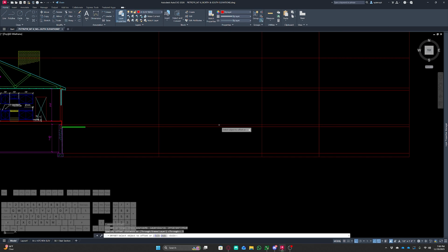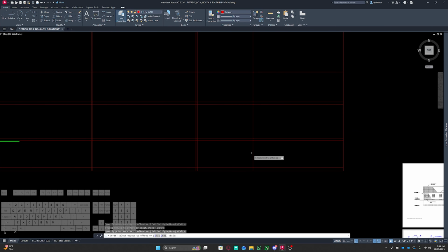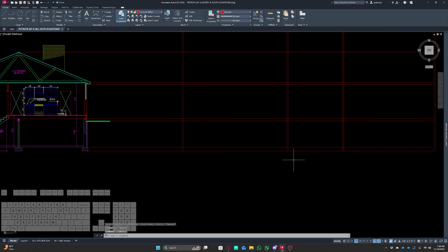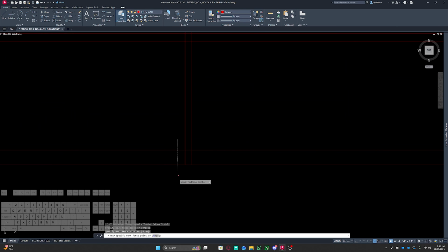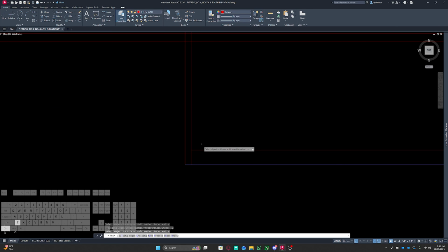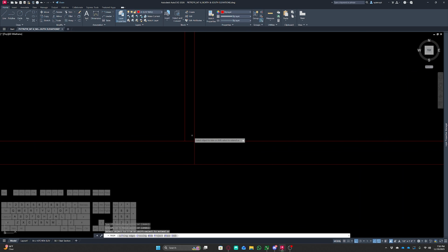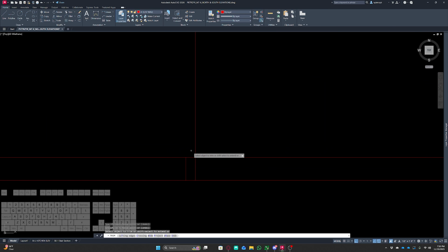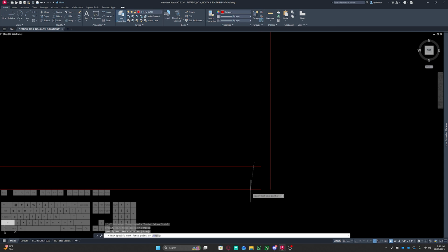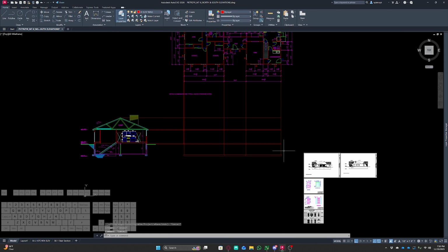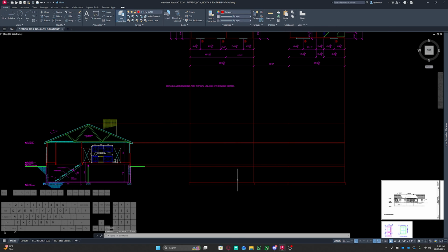I'm going to offset 5 inches. Let me double check. Offset by 5 inches. Yep. I'm going to offset to the left, the right, to the left, and to the right. I'll explain why in a moment, but I'm going to trim. Boom, boom, oops. Boom, boom. Bang, bang, bang, bang, and do an extension. You can see when I'm holding shift, and then I'm going to get rid of that. I'm also going to remove this extension line here.